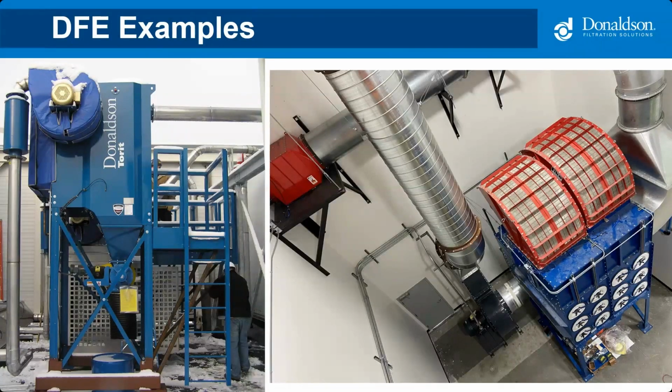So the pressure release is there, the flames are contained within the flameless vents, and when that occurs, that isolation flap valve on the left side slams shut so that any smoke, fire, anything like that doesn't make its way back into the process. The other thing I'll note on this one is you do see some spiral duct there, right? But it's on the return air side.